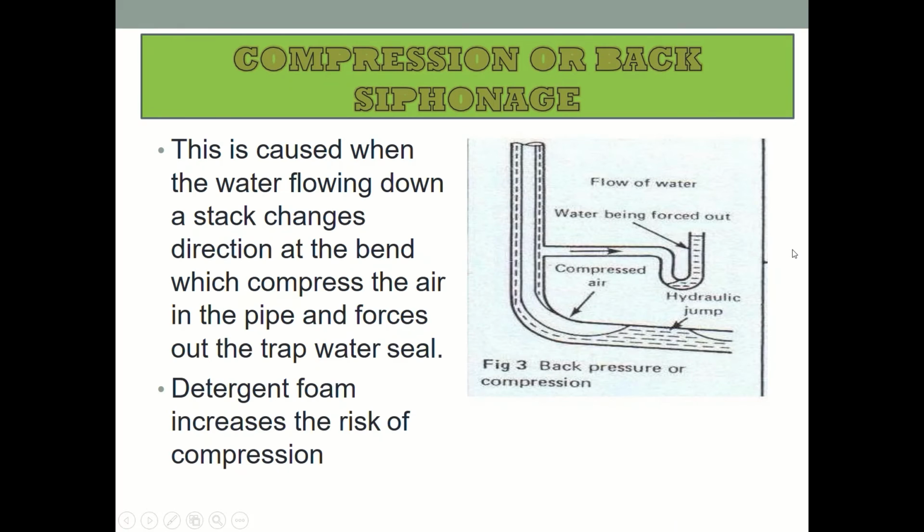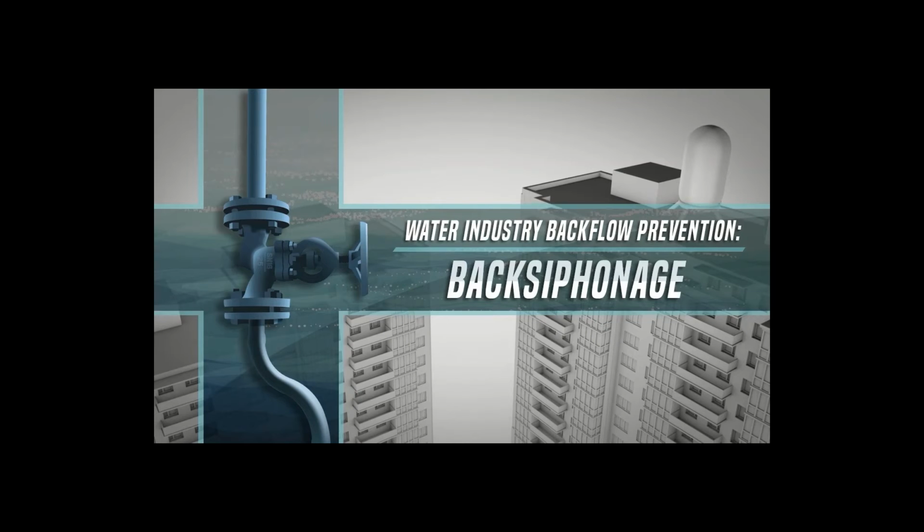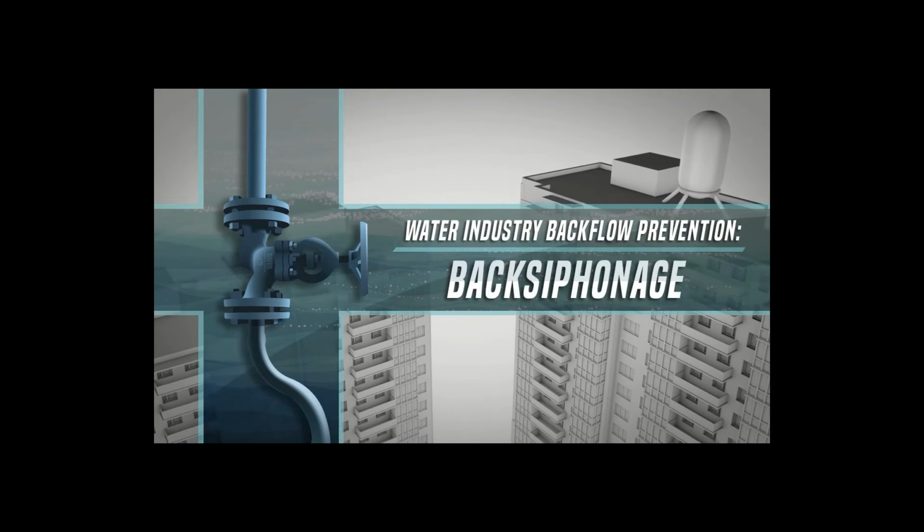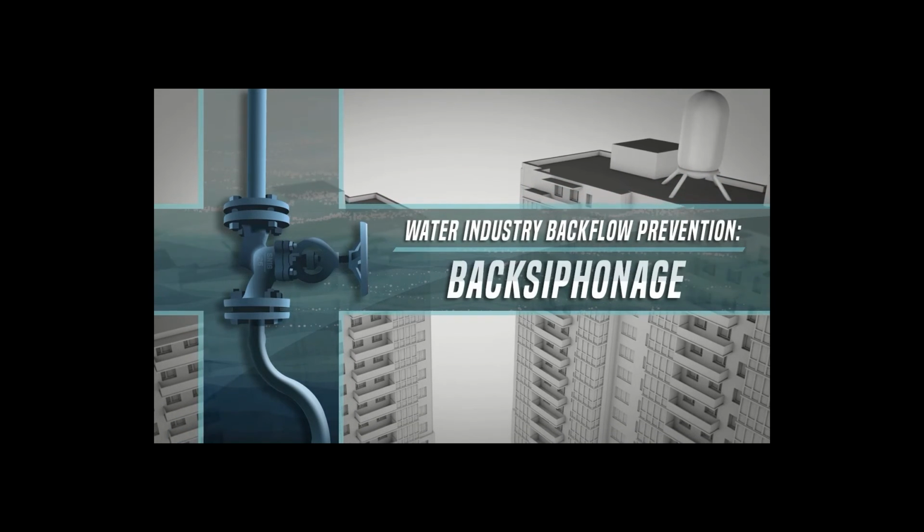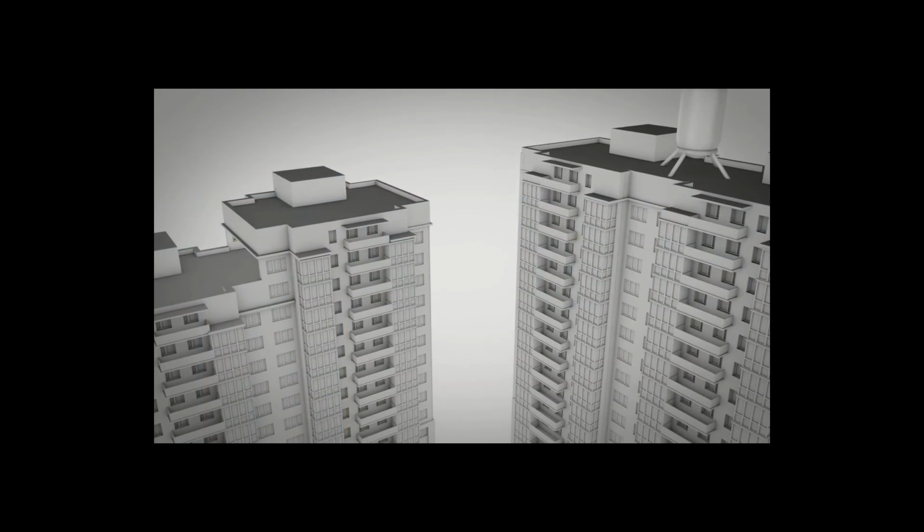So, next, compression or back pressure. This is caused when the water flowing down a stack changes direction at a bend, which compresses the air in the pipes and forces out the trap water seal. Here is an example of back siphonage caused by a booster pump.